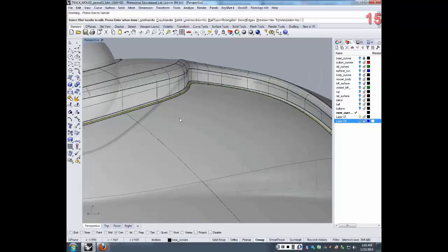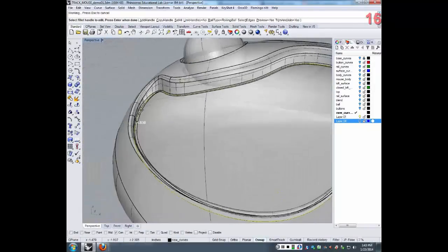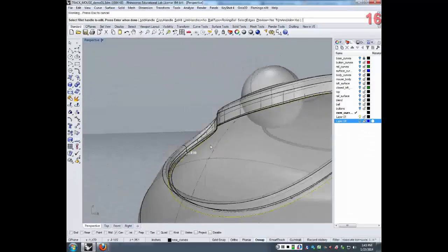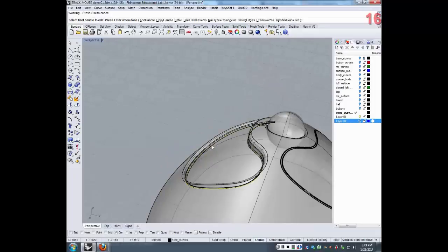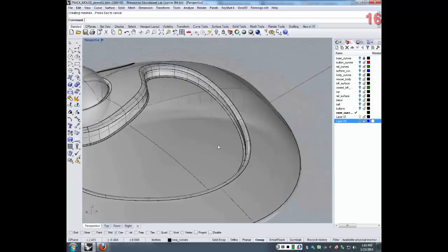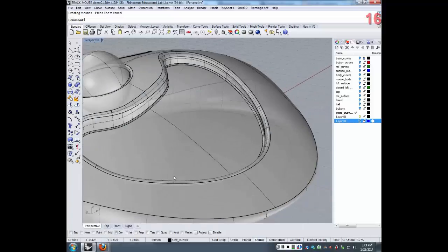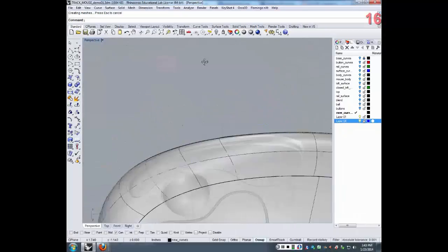Do you follow why you want to make sure that that doesn't happen? You see that? You want to make sure that your fillets do not crash into each other, because you'll get bad surfaces if that happens. And I keep the bottom edge kind of uniform. Okay? And so now I can bring back that surface right here, right?